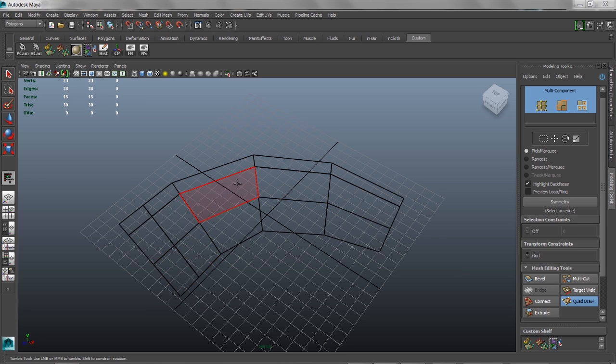In addition to creating polygons, the Quadra tool can be used to insert edge loops and merge polygons. Removing faces and replacing them is as simple as drawing new dots. With any transform tool, you can quickly tweak highlighted components along any axis using the middle mouse button. Tweak mode lets you quickly transform components without making a selection or using a manipulator.